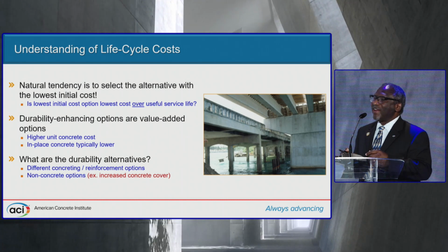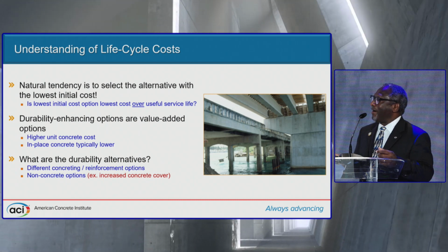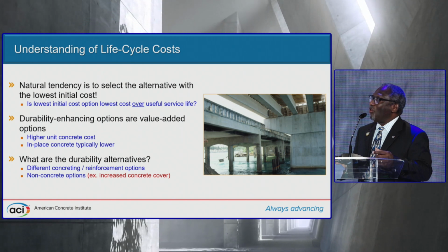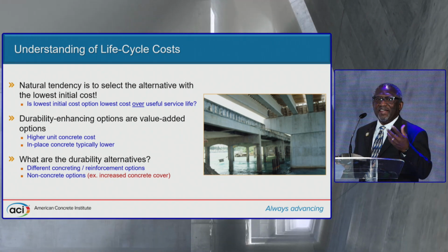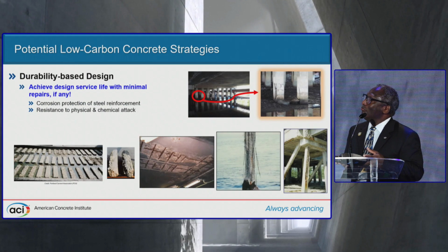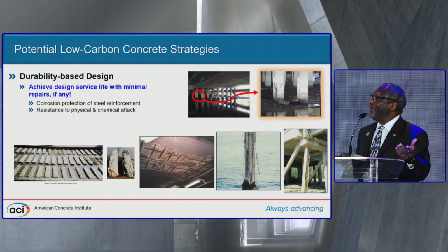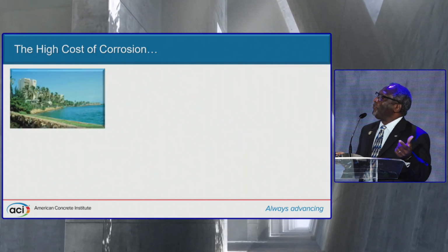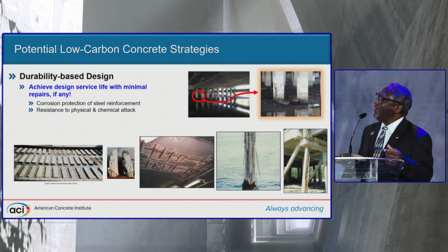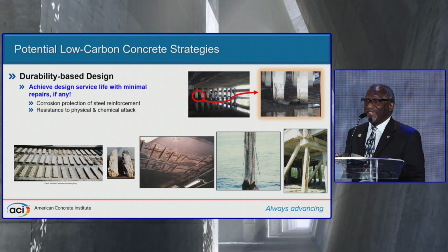Other thing is, what are the durability alternatives that are available? Either different concreting options, such as using geopolymers, reinforcement options, or even non-concrete options, such as increasing concrete cover. So the key strategy, you heard it on Wednesday, you heard it yesterday, and you're going to hear it again from me today. Durability-based design is the way to go to help achieve the design service life with minimal repairs, if any.